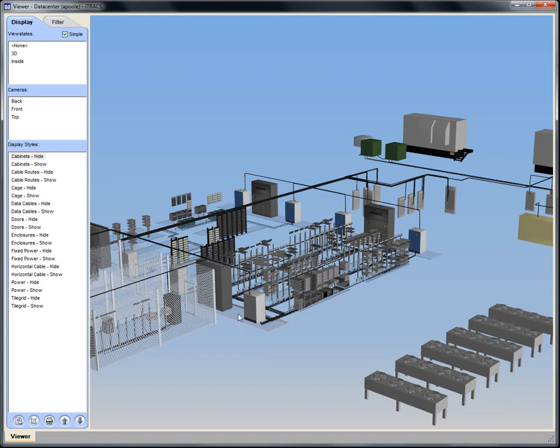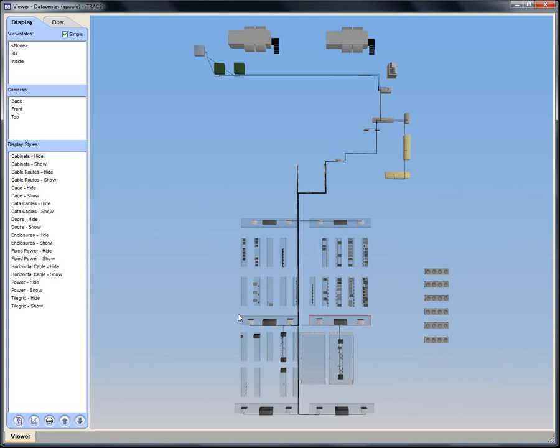We're going to switch gears and talk about the power management of the data center. Here before you is a view of the entire infrastructure of this facility. We are going to isolate the facility down to the power, feeding in from the utility cabinet, which brings us in approximately 4,000 volts. We are going to then isolate this power infrastructure and strip everything out from the view that is not connected directly to the power infrastructure. Here we've done so. This facility is split into two A and B side power circuits across these two transformers.